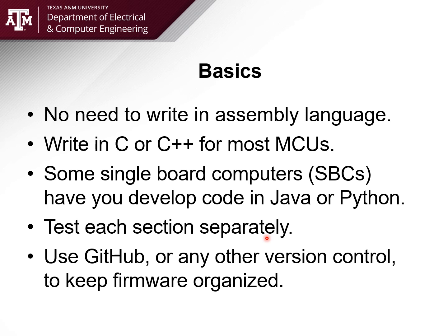Write what's called structured code, which means you want to write code such that the A to D converter has its own separate subroutine. The D to A converter has its own separate subroutine, and you can independently test each part. You want to test each peripheral separately, such that when you get to the main functions, maybe making some intelligent control decisions, the actual lines of code to do that are very short and simple, and those can be independently tested as well. When you combine everything together, all of those independent pieces are tested separately, so you can feel reliable that this should work because everything individually worked, and it's usually just high level stuff, some silliness that you've got to fix.